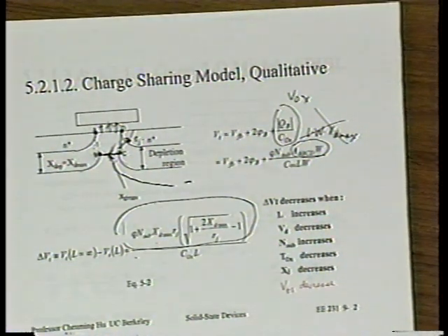Yeah, question. I'm wondering how well does it model the drain-induced barrier lowering, because when the barrier is lowered, the current increases exponentially, and does this model really predict that? That's exactly the right point. This is not quantitatively right.